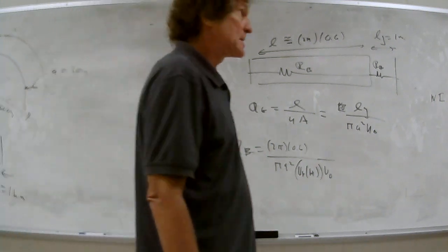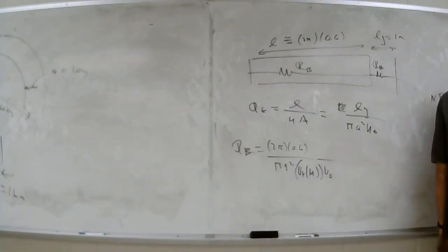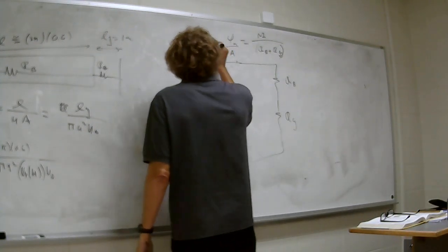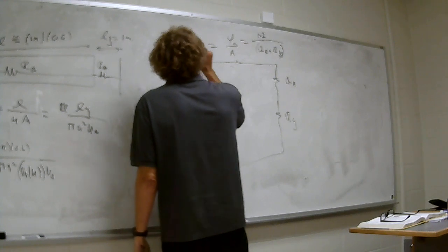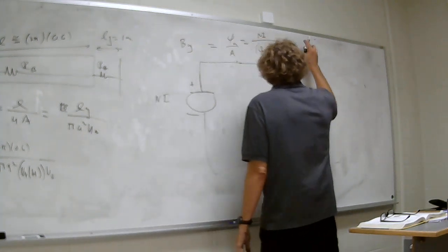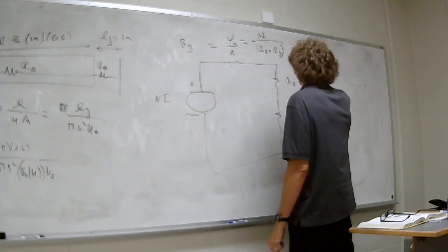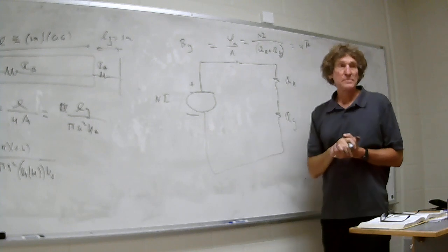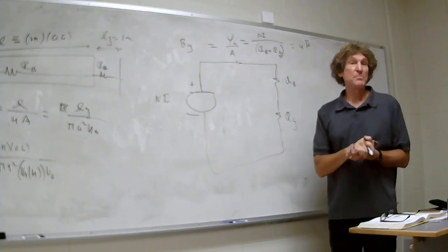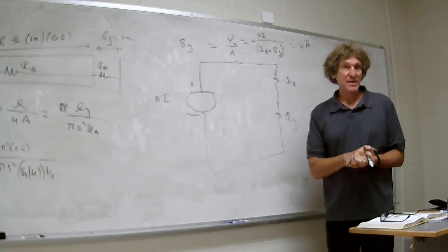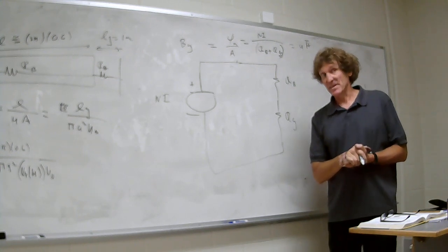First, the B field would be this divided by the area in the gap. So I'm going to divide this by the area in the gap. Now that's the B field in the gap. But we want H, because H is on the horizontal. So if we take this, that's equal to mu times H, right? That would be the value of H in the bars. Here's how we go about this. I'm going to just tell you this is how it's done. You ready?